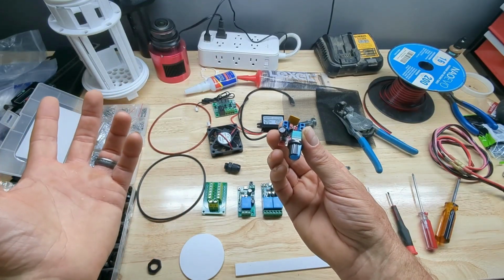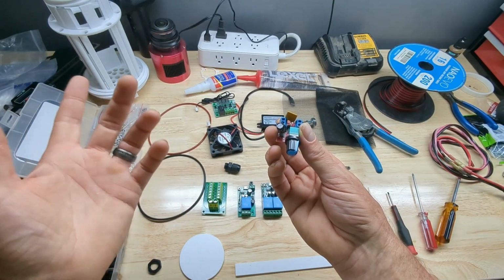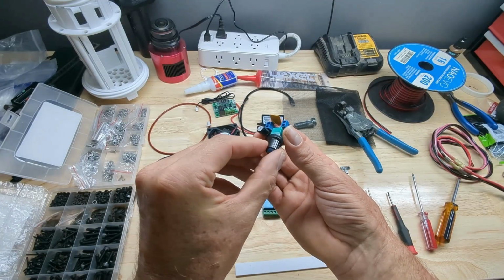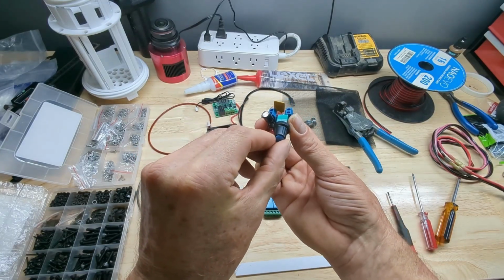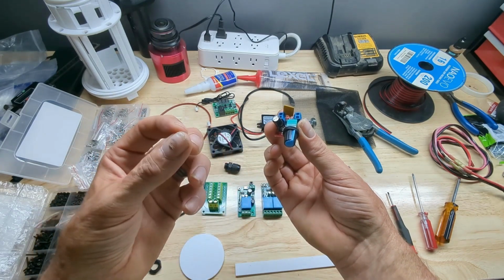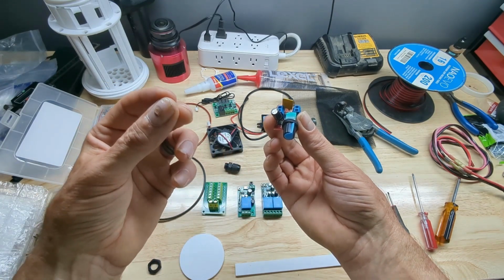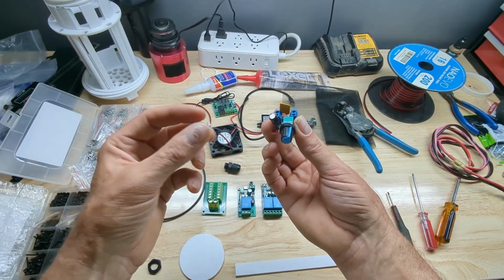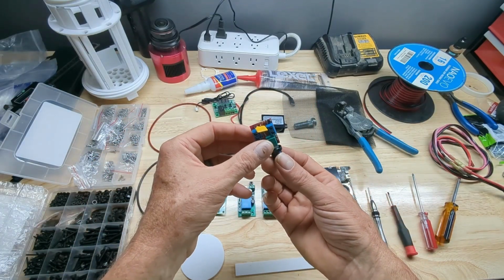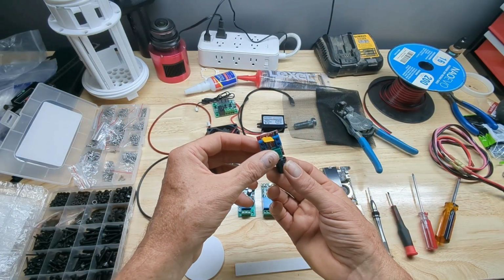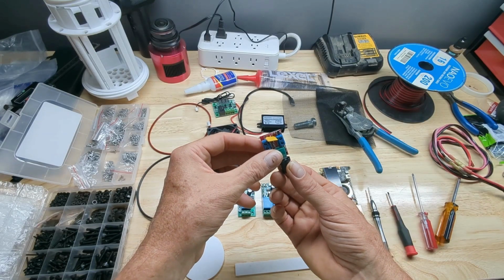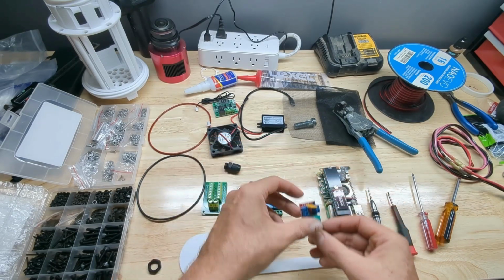Whether you did a DIY dew ring or you bought one from the dew control people, it's good to have one of these because you don't usually ever need 100% power to your dew ring. Normally about 50% is sufficient. You're just trying to heat the dome up just above the temperature on the outside to keep dew from forming. So it's a very nice module to have, and especially with my 12-volt system at my observatory, we need to control as much power usage as possible. So if we don't have to have something at 100%, let's not have it at 100%.